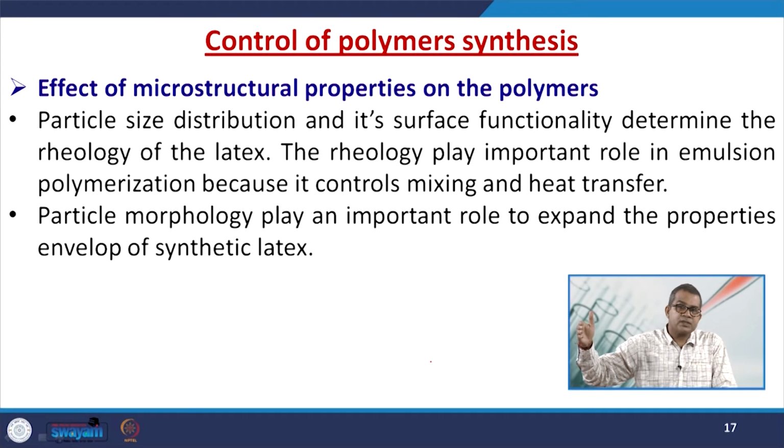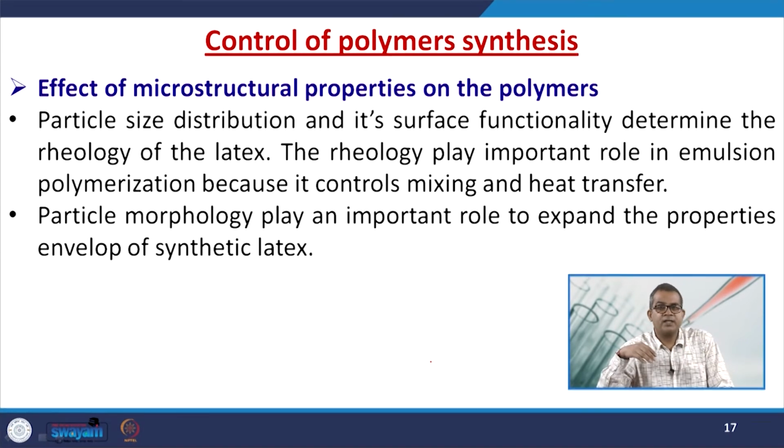The more viscous in nature, then definitely it may create a problem with the mixing, and when there is a problem in the mixing, the mixture may become so viscous that sometimes your mixer will fail. Sometimes your impeller or agitator may fail over a period of time, and if it fails, then proper heat transfer will not take place. So, this particular thing is very crucial.